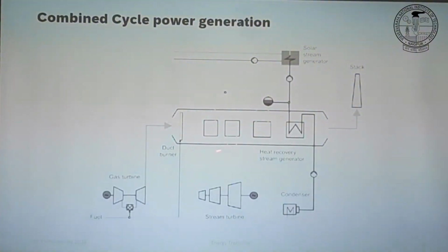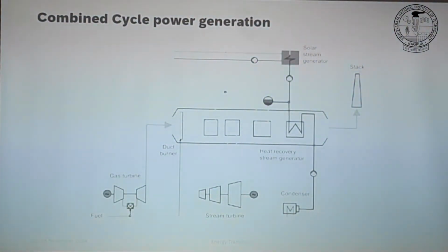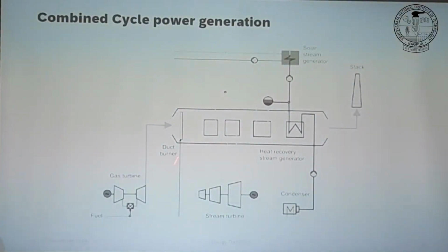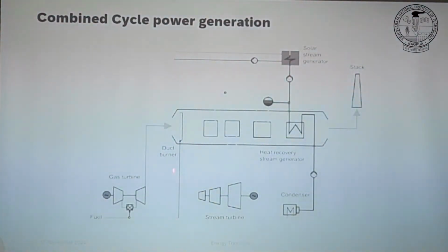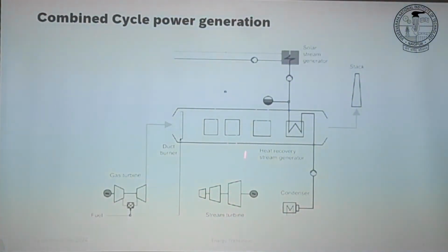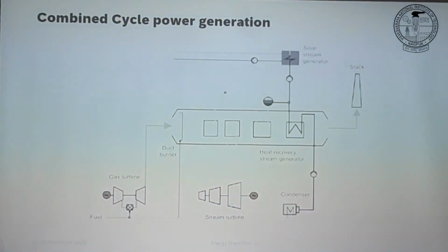You remember yesterday we talked about how we can do air preheating, steam generation and feed superheating, but then suddenly we split the air preheating into two steps, because we want to extract energy at an optimum temperature level. So that's the reason here. You superheat as high as possible, extract the energy, re-inject energy in the steam, put it back in the turbine. That's how you get a little bit more energy extraction. Right.